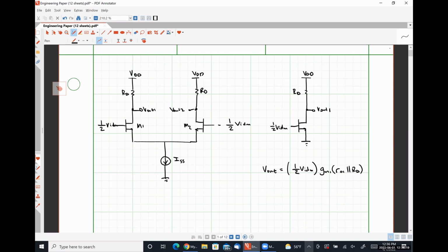So there was a factor of 2 that I was lazy about explaining where it came from, and it caused some confusion. My hope is to rectify that. Effectively, if you analyze the half circuit with Vn applied to the input terminal and Vout taken at the output terminal, you get the gain of the differential circuit. Is that clear? On homework 3, I'd be willing to bet that if the answer you were getting was twice as large as you expected, it's because I explained it poorly and I'm trying to rectify that right now. Are we comfortable with that?